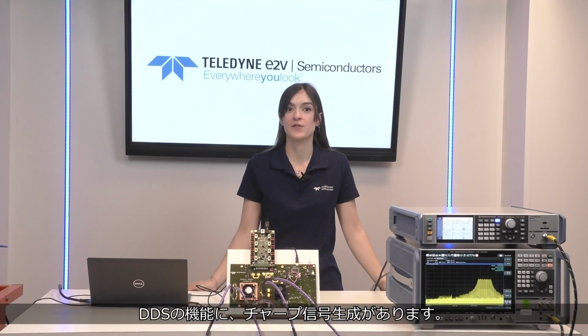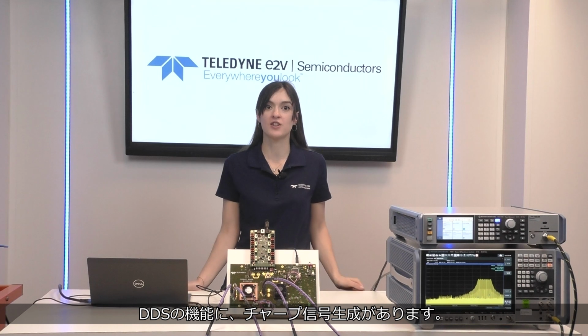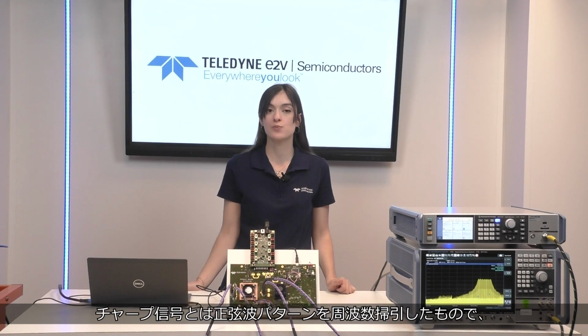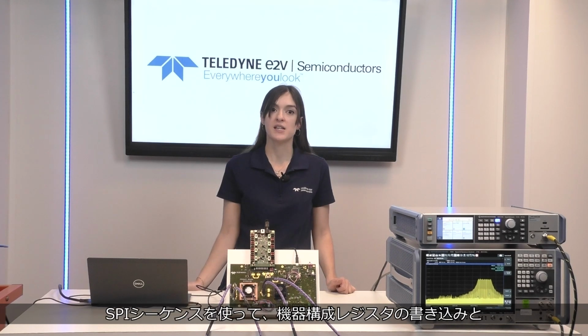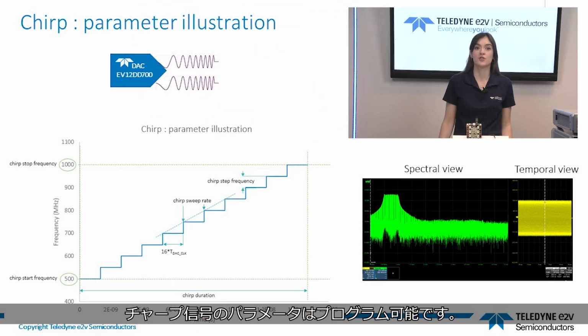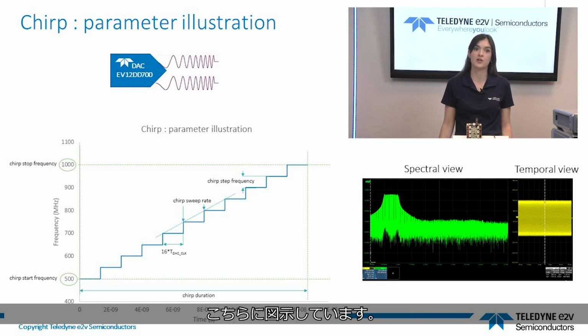One of the DDS functionalities is a chirp signal generation. The DDS allows the DAC to generate a continuous waveform without data samples sent from an FPGA. The chirp signal is a sweep of the sinus pattern generated by the DDS. SPI sequences are used to write configuration registers and to start signal generation. Chirp signal parameters are programmable and are illustrated in this chart.